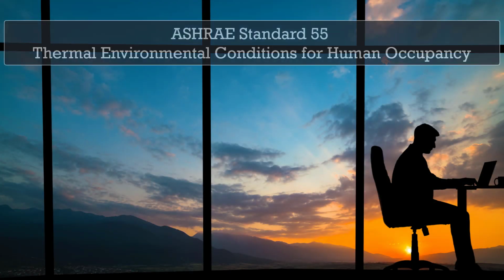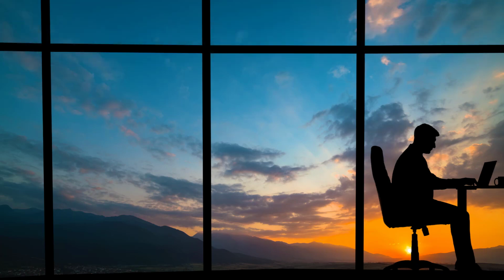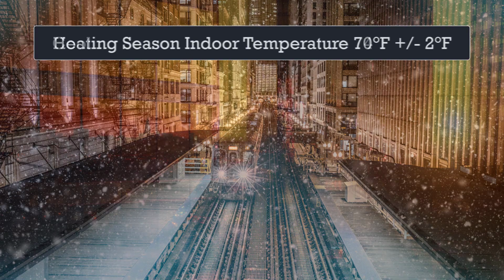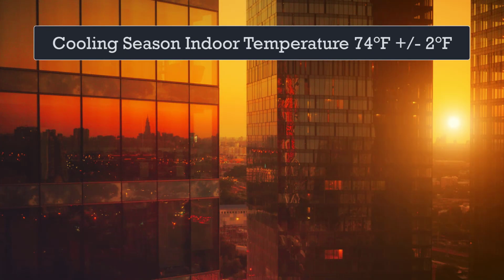While ASHRAE Standard 55, Thermal Environmental Conditions for Human Occupancy, recommends a liberal range of indoor temperatures ranging from high 60s to high 70s degrees Fahrenheit, commercial leases generally stipulate a range of 70 degrees Fahrenheit heating season to 74 degrees Fahrenheit cooling season, plus or minus 2 degrees. The facility manager's measured approach in programming indoor temperatures at the lower end of the humid comfort zone during heating season and at the higher end range during cooling season will reduce building energy consumption.